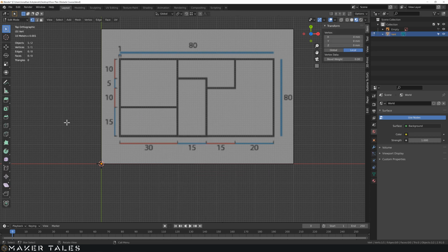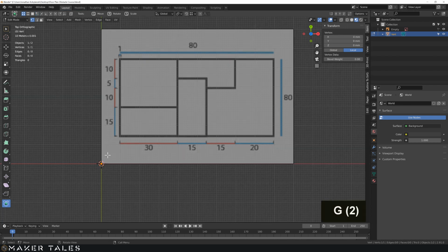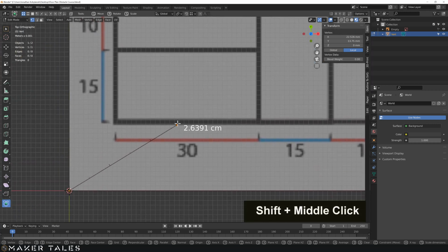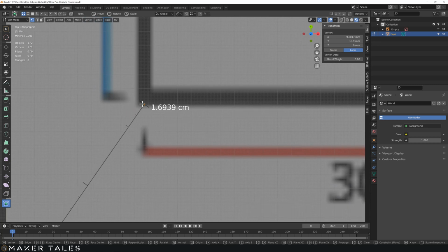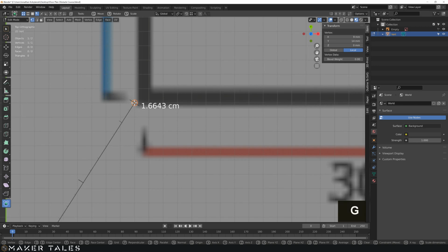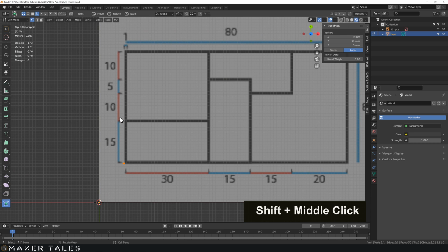We're in edit mode now. So let's turn on CAD transforms. Let's hit G for move. I have my grid up already. So let's move this, and I'm going to call this grid here the bottom of the wall. So I'm going to hit G for grid snapping, and snap to that grid there. Okay, great. So now with that there, technically I don't need these measurements, but I'm going to use them.